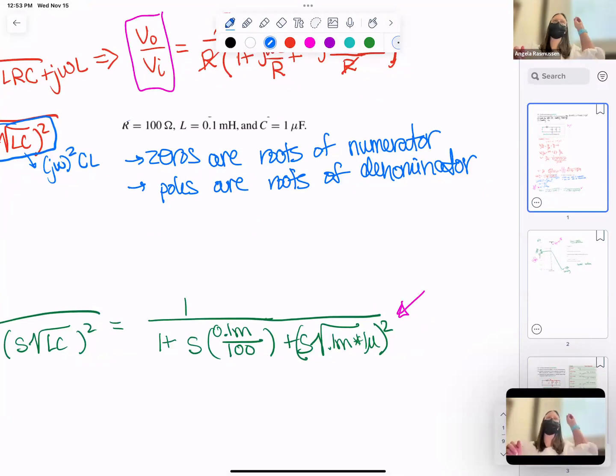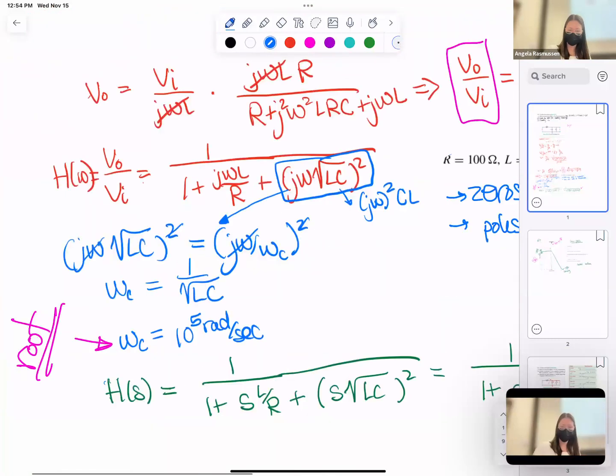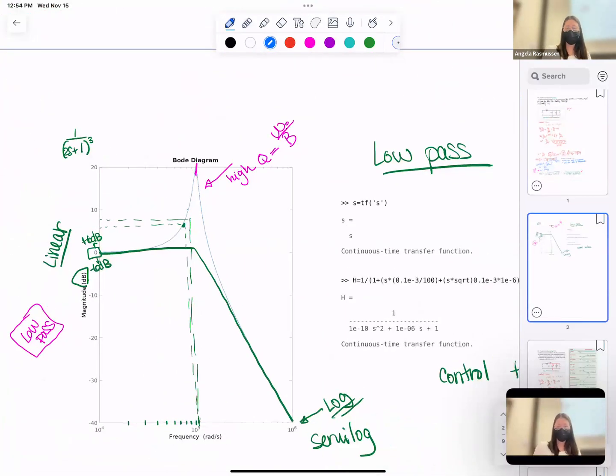And these are going to be just specific frequencies where you're either going to have a corner frequency or a cutoff frequency, or have a change in this graph. So we've only looked at filter graphs, but there are other forms of this graph. One is an amplification graph, where you can have changes that don't look like low-pass filtering. With those, the poles and the zeros are going to give you basically just a change in this magnitude graph.